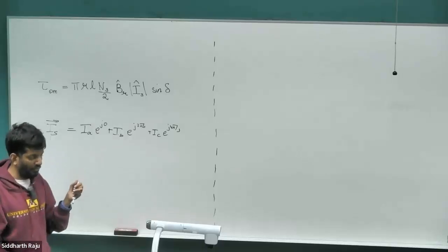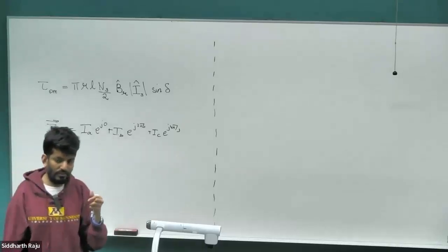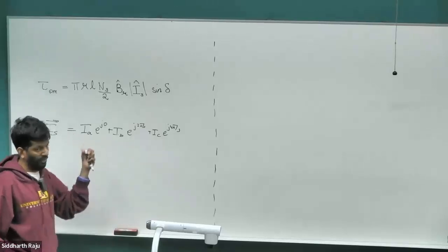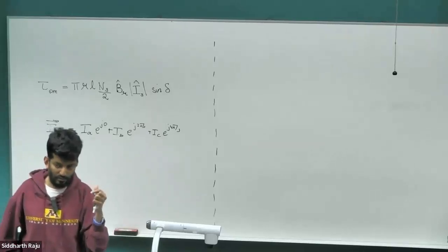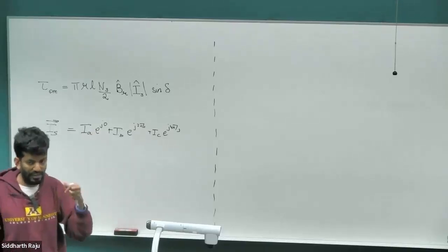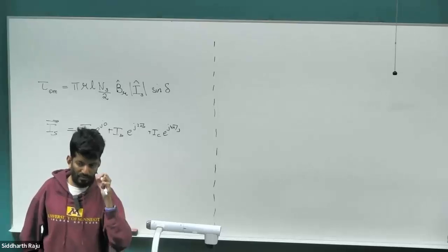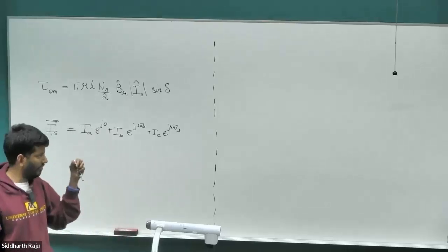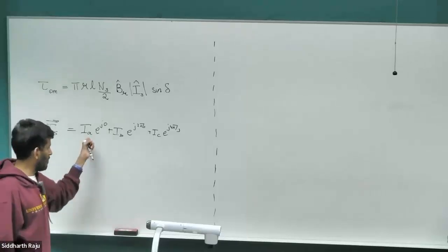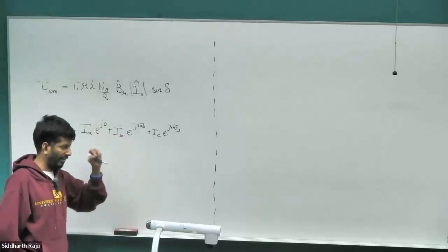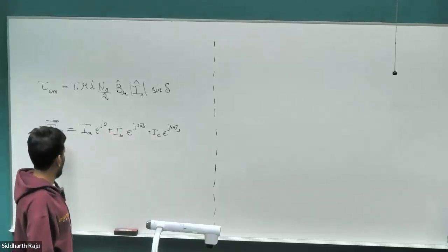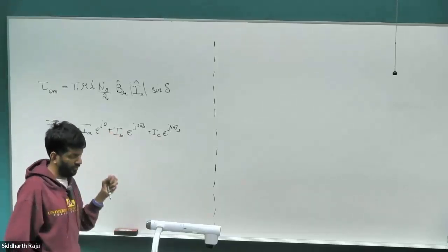But there is another way of doing this as well. Why restrict ourselves to just scalar weights? We can use vector weights. In this case, we are using a unit vector, the scalar magnitude of the vector is 1, but we are putting weights along different directions. In a scalar case, we are putting weights along one direction, but with different magnitudes. In a vector case, we can have different magnitudes and different directions. We are choosing to have the same magnitude and different vector directions through which we are weighting these three values and then summing them to get a vector weighted sum, which is the space vector transformation.